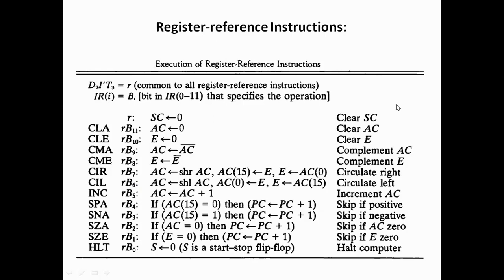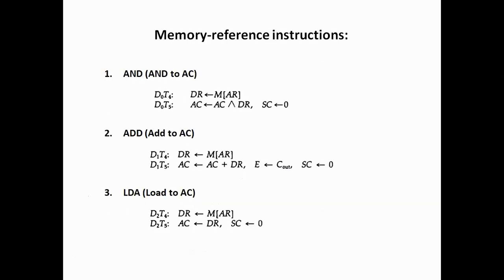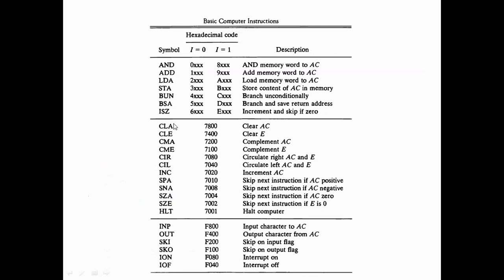And for the same, we can also see the hexadecimal here. If I want to put those 16 bits of the instruction format in hexadecimal, what will it be like? The first 4 bits are 0111, that is 7, and then followed by 1 and 11 zeros, that means in hexadecimal, 7800.